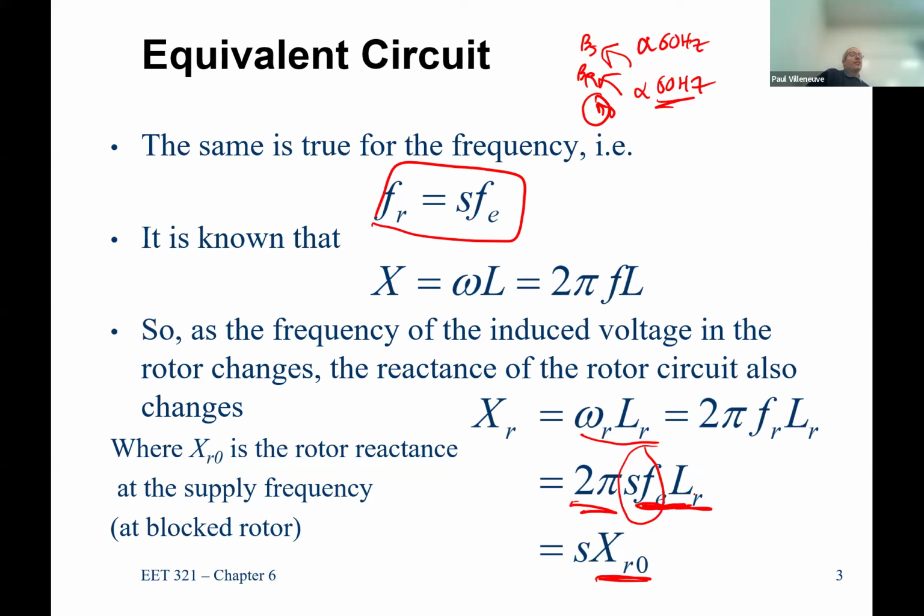Remember, with circuit analysis we assume AC steady state conditions. If we have one system that's operating at 5 hertz and another one that's at 60 hertz, you can't analyze them using steady state circuit analysis. So by introducing this S term over here, it allows us to use an electrical frequency of 60 hertz, and we get the results that we need.